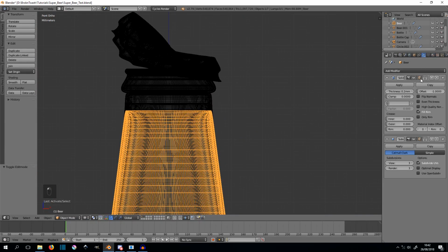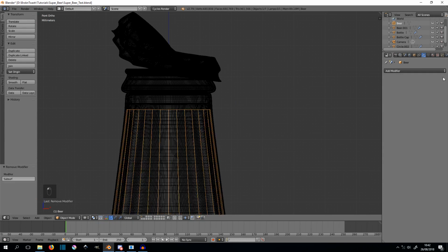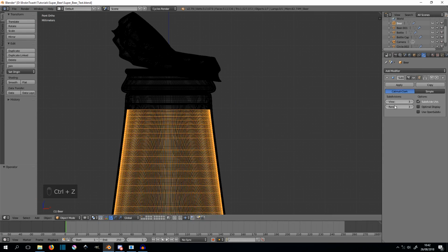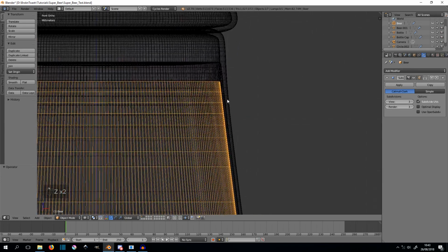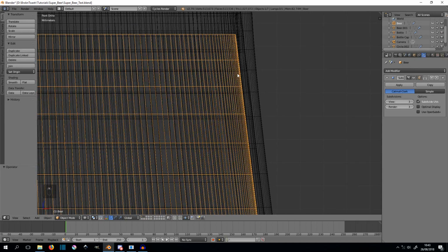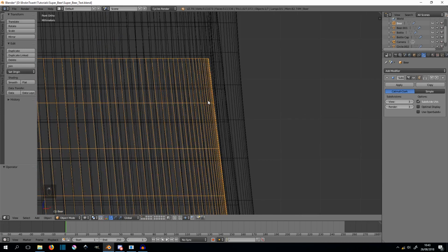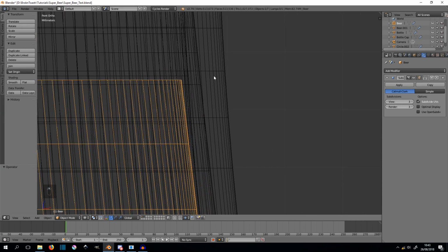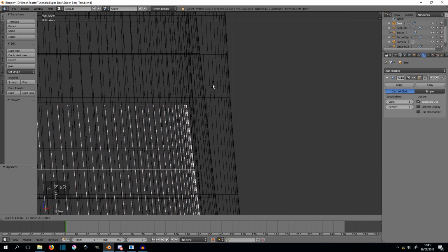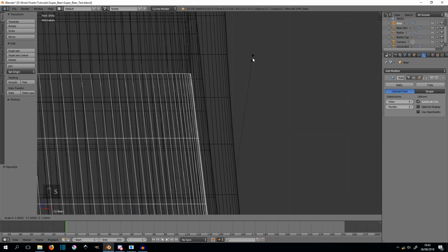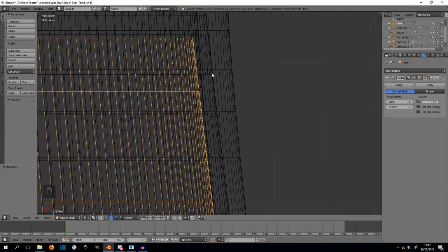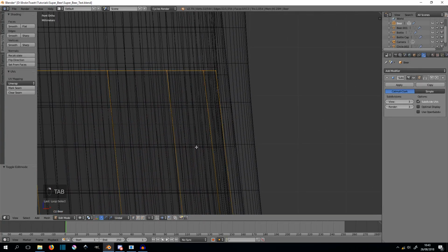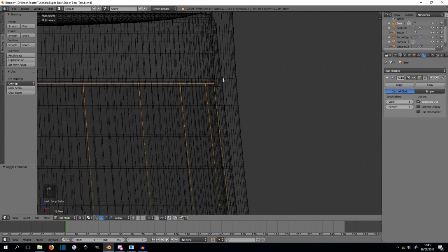Also, before that I will turn off the solidify modifier. Oops, I pressed 2 times. I just want to get rid of the solidify modifier, because obviously our beer is not a solid object, it's a liquid. And the other thing I'm going to do is resize it so that the beer is between the limits of, or between the thickness of the bottle.